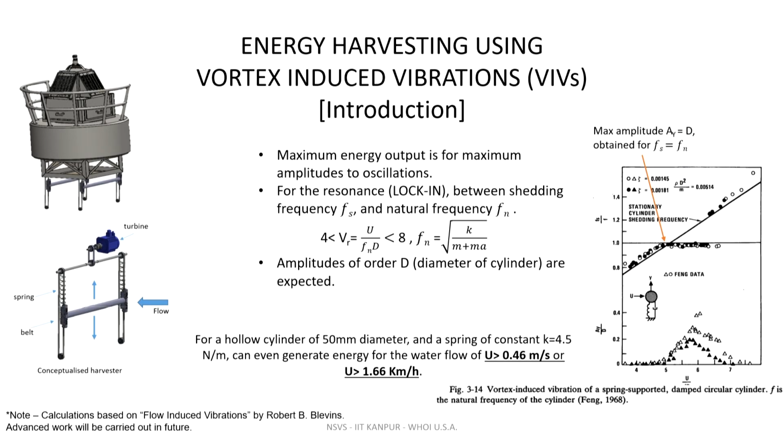And then the other system we have used is called vortex induced vibration, or VIV. In the VIV, this entire body works like a bluff body, and hence the water coming from the upstream creates vortices on two sides, and these vortices can vary the lift force.